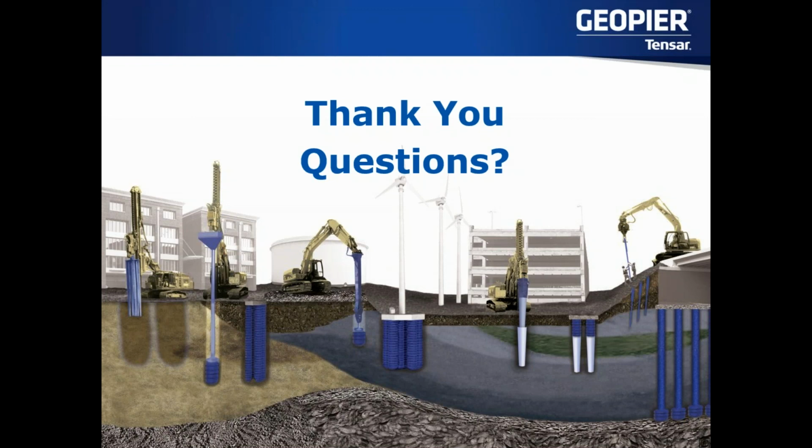When we run a modulus test, you get a raw indication of the pier stiffness. It's more conservative because it's a single pier. You're not testing group response, and it costs dramatically less. It's 10,000 versus 100,000 or more to run a modulus test versus a full-scale test. I could talk about that for a while and some of the frustrations I've run across in projects, but hopefully that's a short answer.